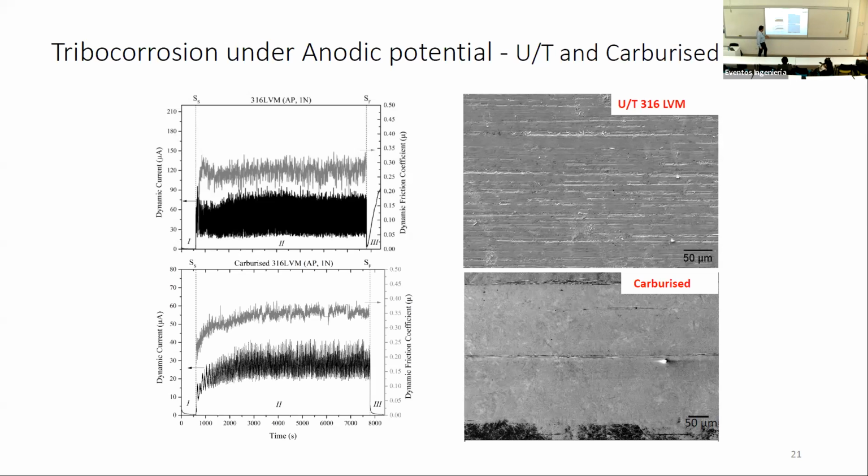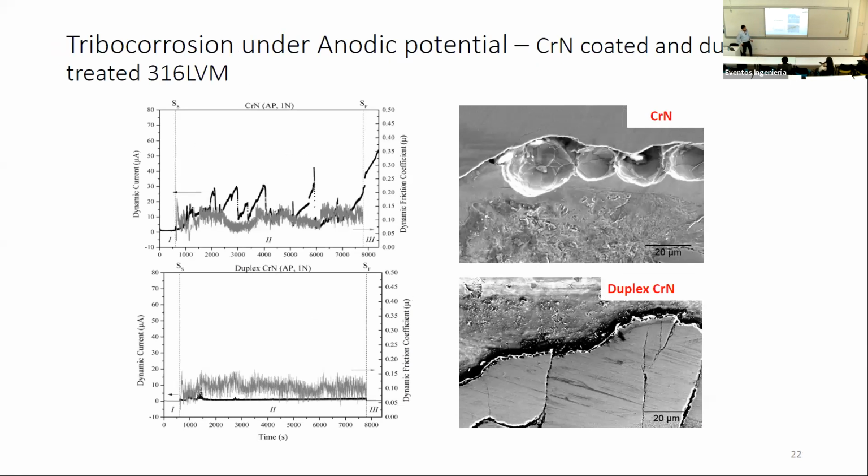When it comes to the carburizing, we're still getting a lot of oxidation, type 1 corrosion wear, less wear due to corrosion. For the coatings, we got, in this case, very bad results. Within the wear scar, it's not just the coating failing, but we could see these features here, and those are pits within the stainless steel. So the material underneath the coating was pitting, and we were getting these large holes, depressions inside the material.